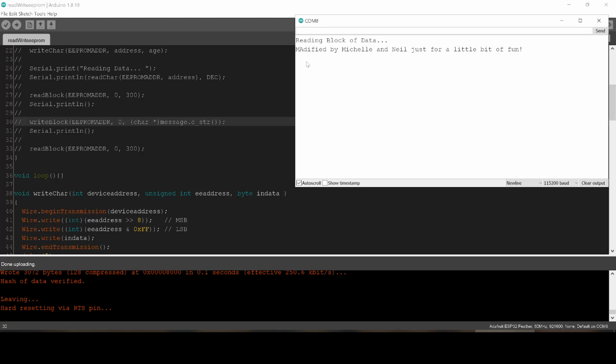My next step is being able to read from the EEPROM via the FPGA, that code. And then I also need to work on being able to send over and read from the microcontroller that's built into the FPGA, so I don't have to keep plugging it into my ESP32 microcontroller. So those are the next steps in this design, but I thought I'd report in on the progress we're making. I hope you enjoyed this video. But there you go. We've actually programmed this I2C EEPROM via my FPGA. Thank you and have a good day.